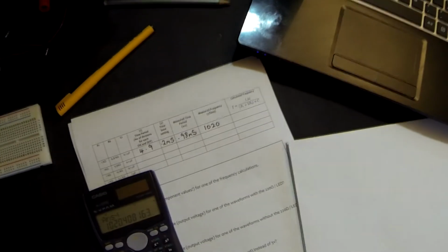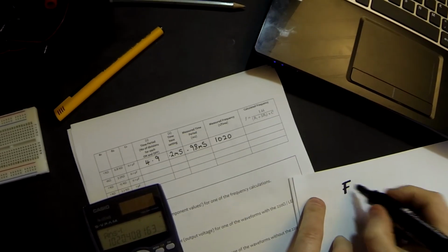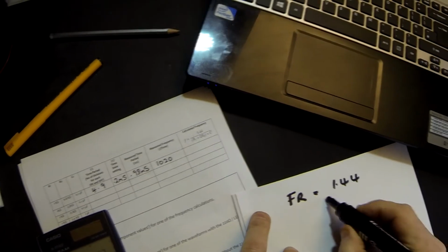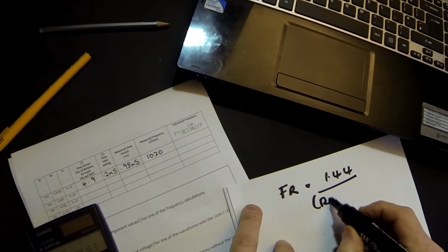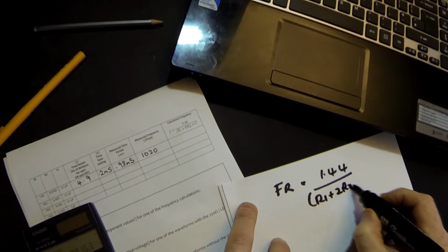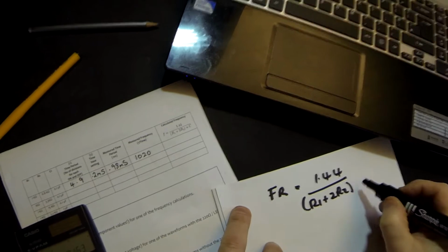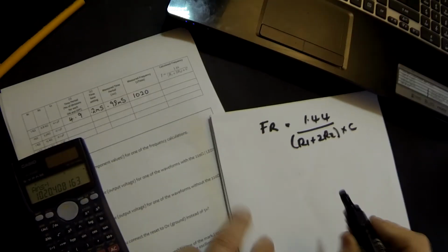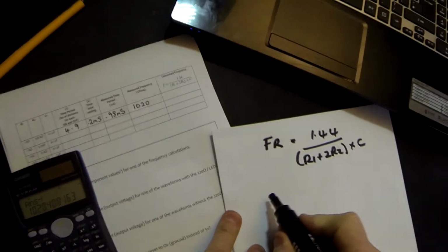So let's have a little look at our formula and see how we can fit this into our calculation and compare it to our answers. So already in the information sheet, it tells us that frequency is equal to 1.44 divided by R1 plus 2 times R2, and they need to be worked out first, times C. Now there are many ways of doing this. It depends how good you are with the calculator. So that equals